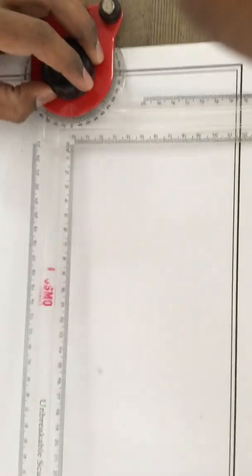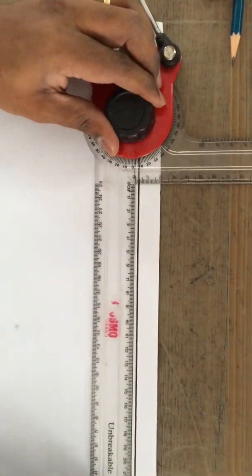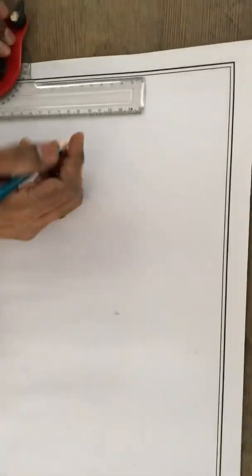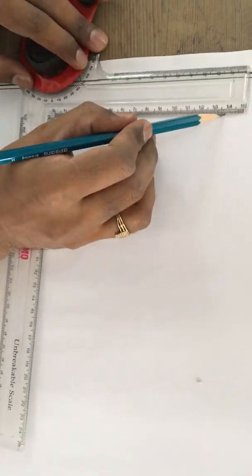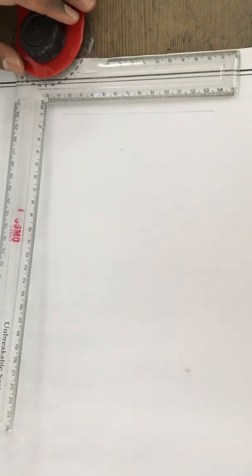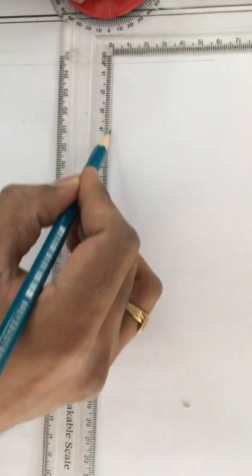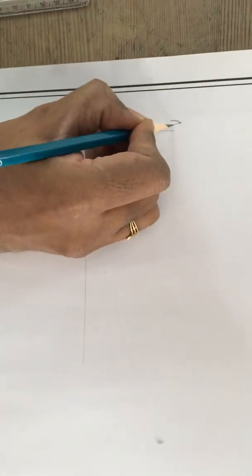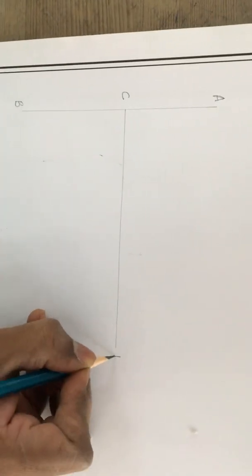Now I am going to show you how to draw the construction of a parabola using the eccentricity method. Dear students, this is how you are supposed to fix your drawing sheet as well as the drafter. Now with the H pencil, draw a line of any length. Let that be a directrix, and also draw a line perpendicular to the directrix, stating that as the axis. Let this AB be the directrix and CD the axis.